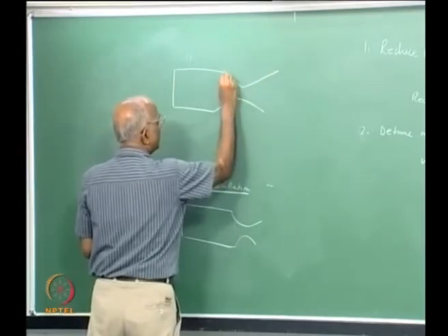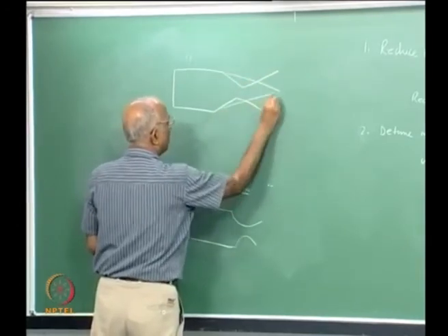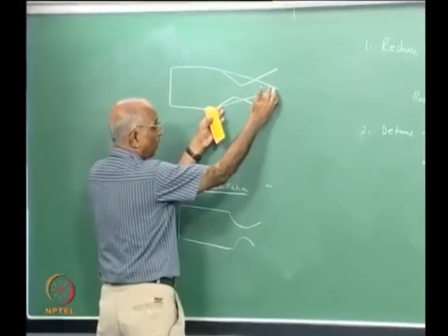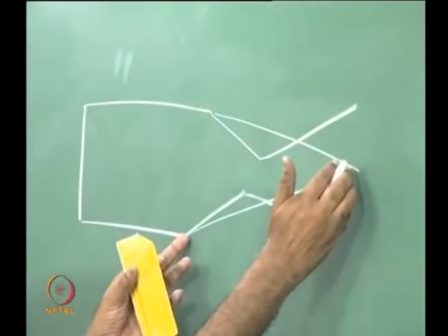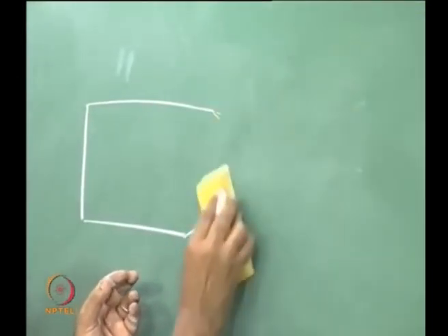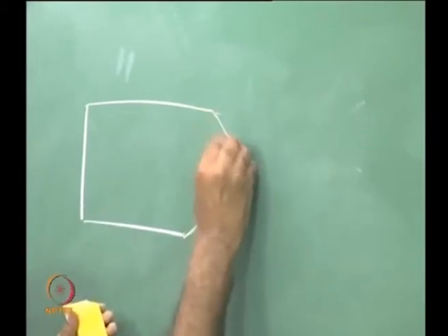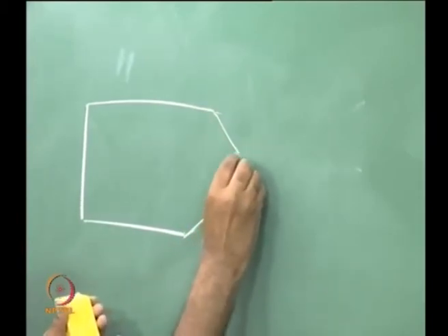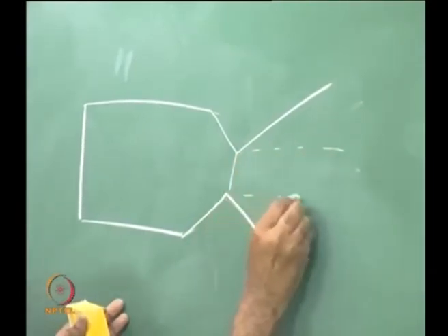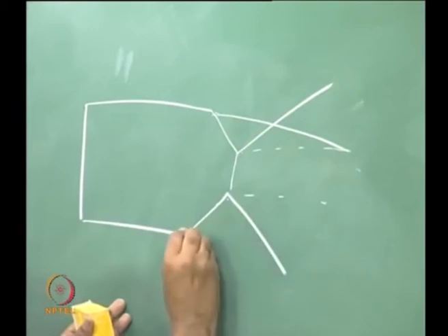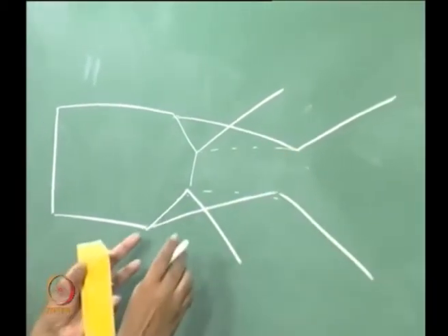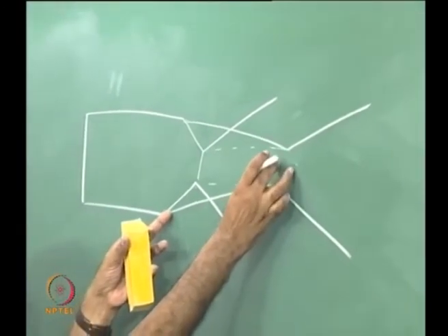If I can make the convergent much longer, that means the rate of density variations is quite smaller, because now my density variation for the same throat size, let's replot it. Initially this was my throat here, this is the area of my throat, I have a divergent. Now instead of this I delay it over here, I get something like this, and now I have my divergent here. That means my rate of density variations is much lower.